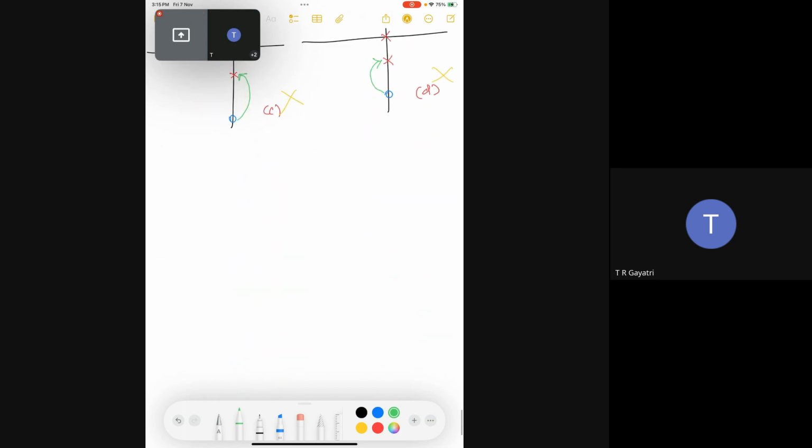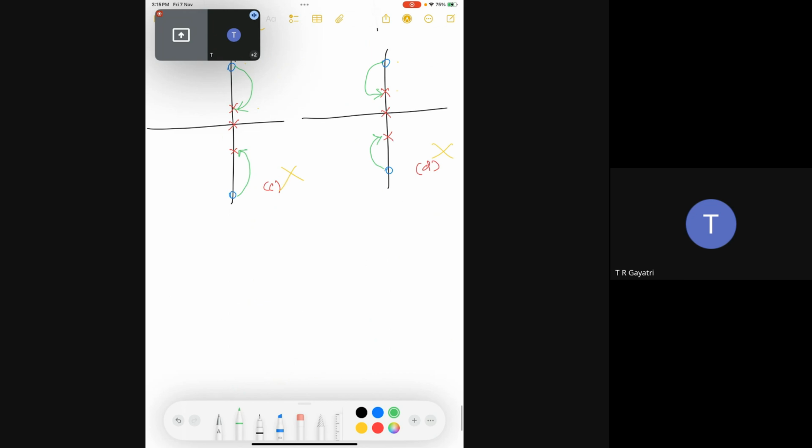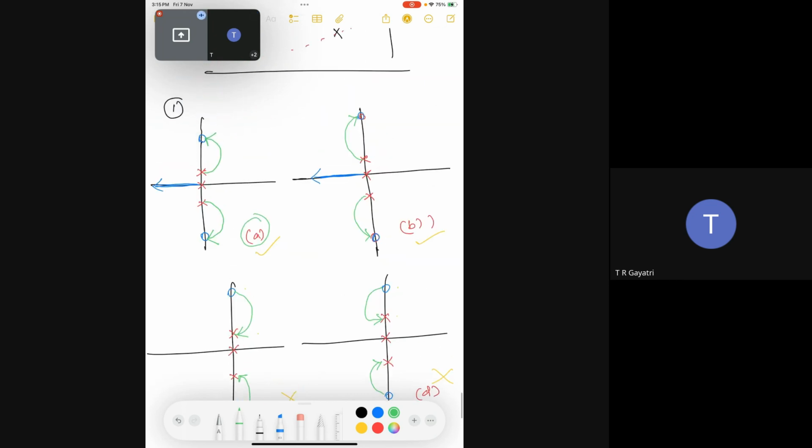Calculate this theta equal to 180 degree plus sum of angles from poles minus sum of angles from zeros. So for the zero, we don't have an exact value, just put some arbitrary value.